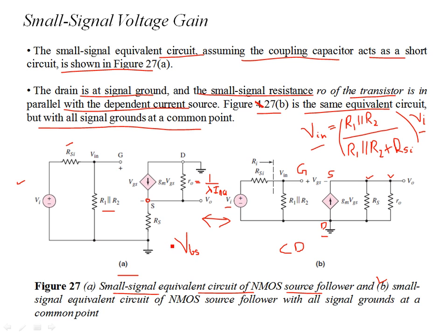Due to that, you have a back transconductance gain, gmb. And owing to this, you have to consider another current source in the small signal transistor model besides gm VGS. But we are not considering this back transconductance gain, so we are neglecting the body effect.